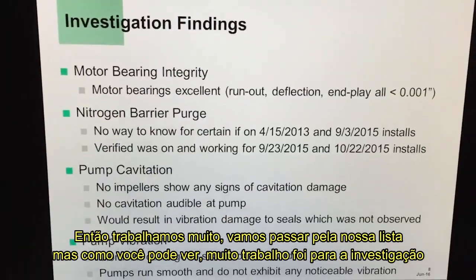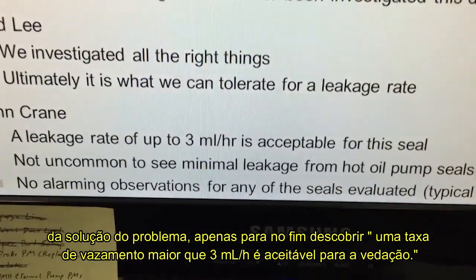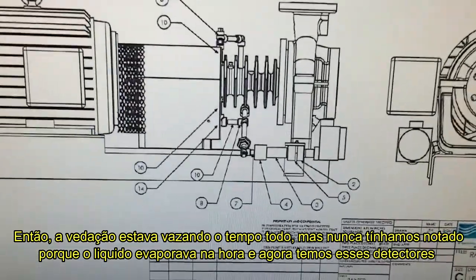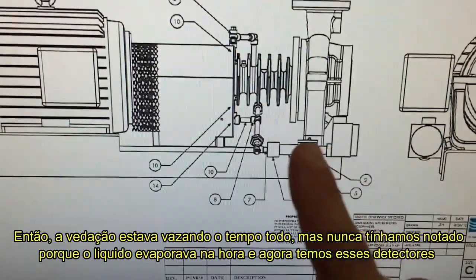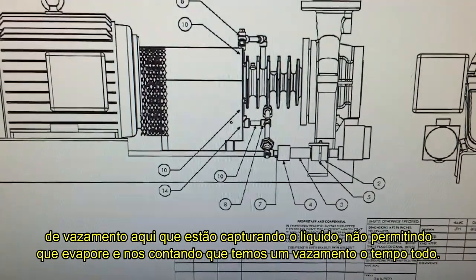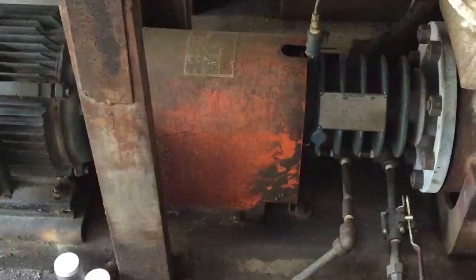We won't go over all this, but as you can see, a lot of work went into the problem-solving investigation, only at the end to find out a leakage rate of up to 3 milliliters per hour is acceptable for this seal. So the seals were leaking all the time, but we never noticed it because the liquid would evaporate right away, and now we have these nice leak detection systems on here which are capturing the liquid, not allowing it to evaporate, and telling us we have a leak all the time. So we had to solve the problem to account for the normal leakage rate for the seal, and we'll take a look at how we did that next.